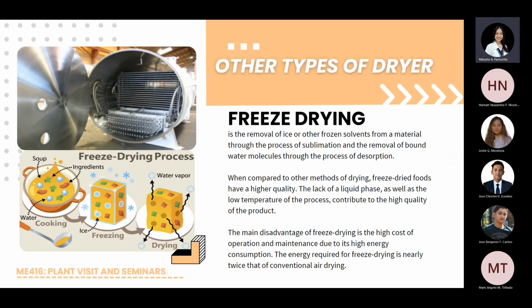Freeze drying. Freeze drying is the removal of ice or other frozen solvents from a material through the process of sublimation, and the removal of bound water molecules through the process of desorption. Sublimation is the direct transition of water from a solid to a gaseous state that does not involve melting. When compared to other methods of drying, freeze-dried foods have a higher quality. The lack of a liquid phase as well as the low temperature of the process contribute to the high quality of the product.